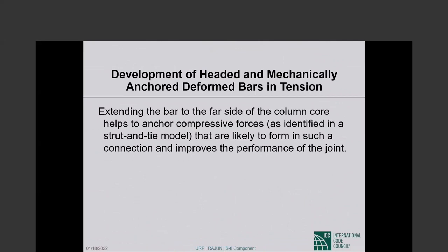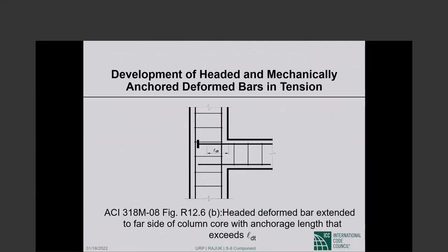Okay, continuing with development of headed and mechanically anchored deformed bars in tension, extending the bar to the far side of the column core helps. There is one slide of writing. What this is saying is something very sensible.